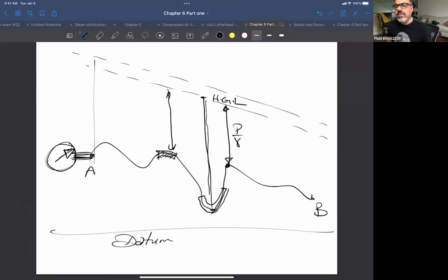There's a pressure at the pump here. So in this problem, the maximum pressure or the maximum schedule that you're going to use for this thickness, is it closer to the pump, or could it be somewhere else? Closer to the pump. Okay.